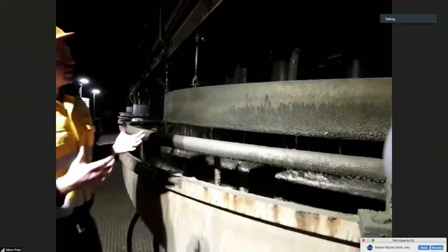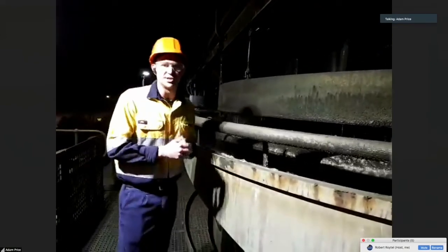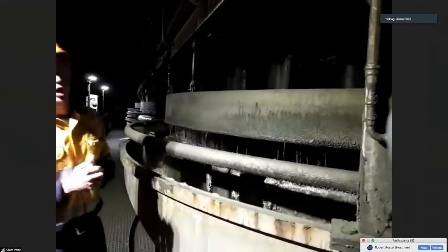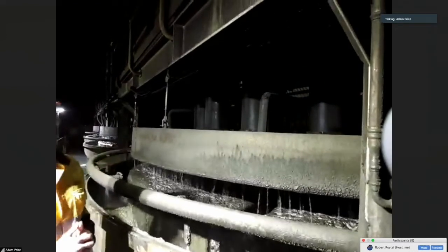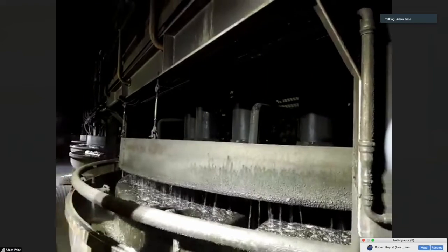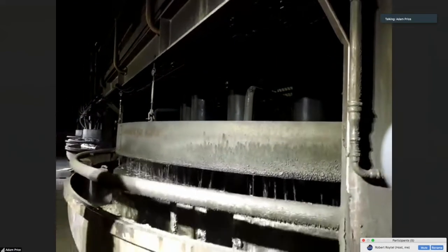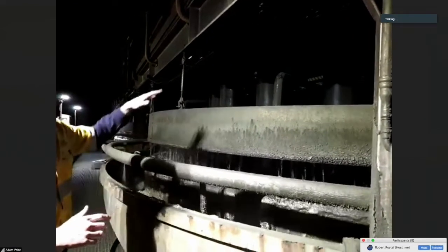So to give you a picture, you obviously can't see inside these downcomers, but I'll try and give you a visual aspect as much as I can of what happens inside there. Essentially, we'll have some preconditioned feeds that'll come in and feed up at the top of the Jameson cell. We'll have a good look at the top of the cells in a minute. But this feed will be sent to a distributor, which then will evenly divide the flow in amongst the downcomers that are in service.